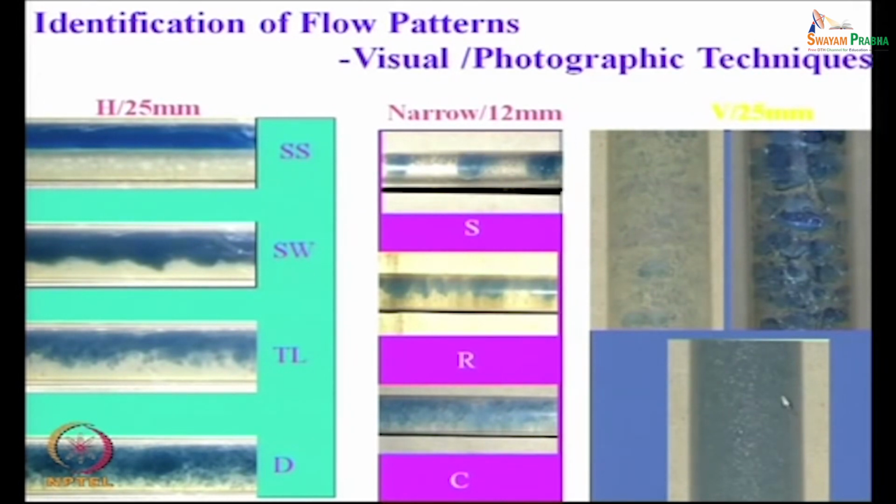On the contrary, when we go for high kerosene and low water velocity, the entire cross section becomes blue in color, meaning that kerosene is a continuous phase, and in that bluish cross section we find small droplets of water dispersed. So, this phenomenon, the inverting from one continuous phase to the other, as I have already told you in the last class, is phase inversion. This occurs for liquid liquid cases and never for gas liquid or any other two phase flow situations.